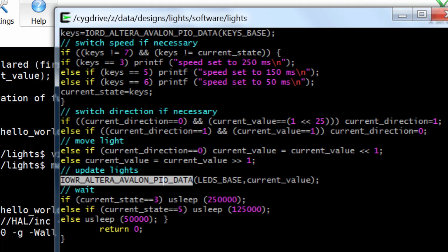Now you might say, what value do I write in? Well, that depends on what you want to show up on the hex. If all 8 hex digits are separate, each one is going to be 7 bits. So you have to have in mind what you want to show up, and then you have to convert that to a number that you want to put on that hex display. Now keep in mind that these are active low.